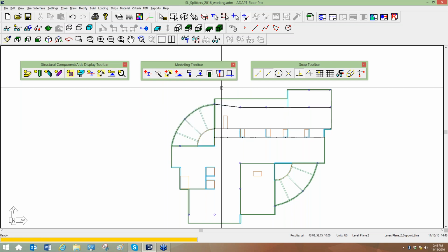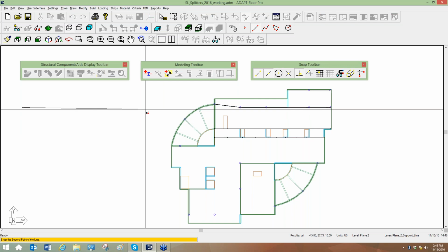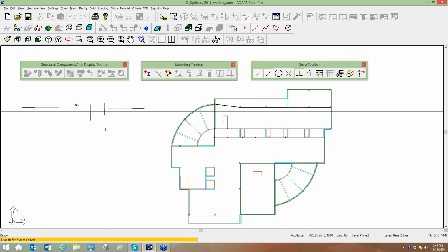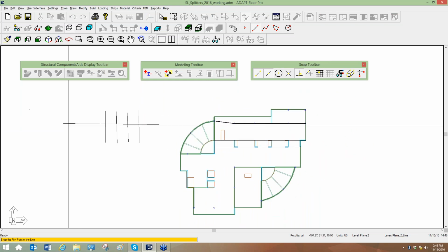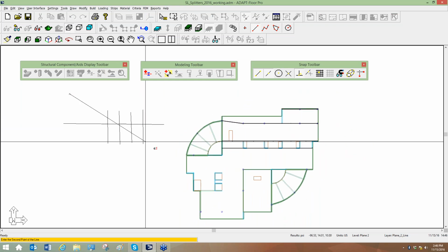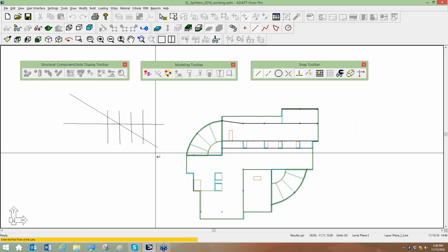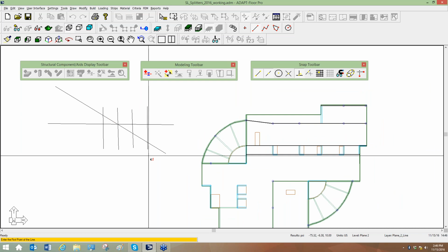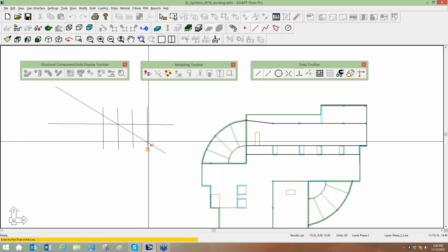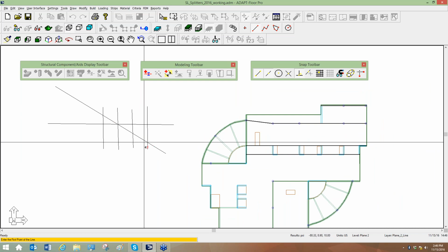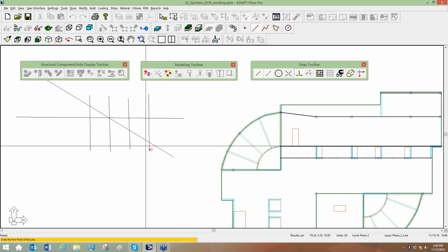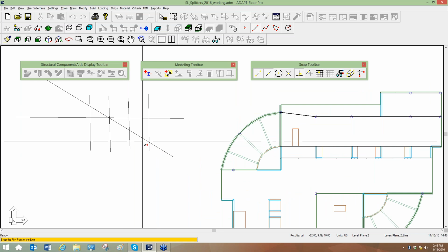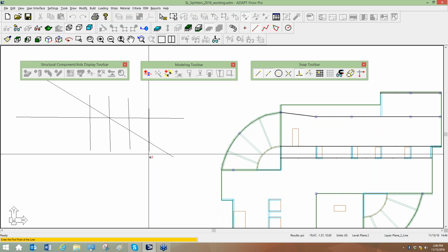So what I mean by that is if I have a design, here's my support line, let's say, and I have a bunch of design cuts, and let's say my tendon direction is like this. This is my banded tendon. That banded tendon is intersecting these design cuts, but it's intersecting it at an angle. Let's assume it's 45 degrees. So you're really only getting a contribution of the PT relative to the angle at the design cut.